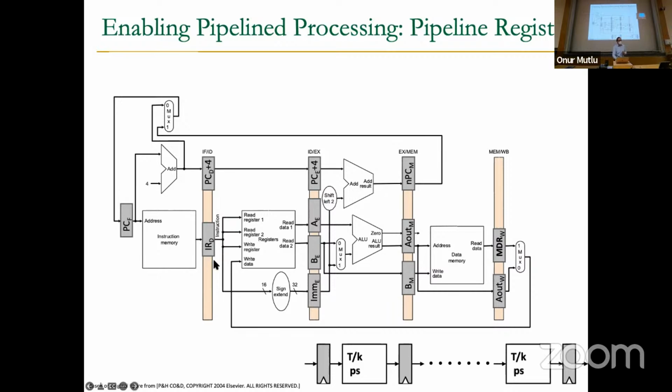But basically, at the end of the stage, you have the instruction in this pipeline register. In the next cycle, this instruction is going to be decoded as well as it will access the register file, right? That's that stage. Very similar to what we have done earlier. While this is happening, PC+4 is being fetched because PC+4 was incremented while this instruction that you're decoding was here in the previous cycle.